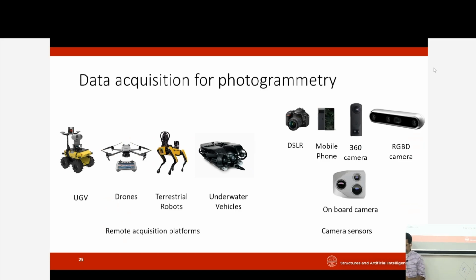So that's sometimes a problem with photogrammetry, but there are some undistortion methods as well that can be applied, and these are also available in many of these proprietary packages, including RealityCapture. If you know surfaces that should be planes, then that can be useful in making sure that your model is not warped.